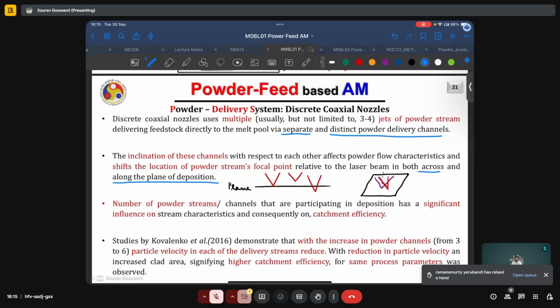For this reason, part of the powder will bounce off the track because of the high velocity of the carrier gas and the high exit velocity the moment it leaves those outlet tubes. Secondly, the laser power may not be sufficient to melt all of the particles, and some of them may remain unmelted and just bounce off or fall to the sides.